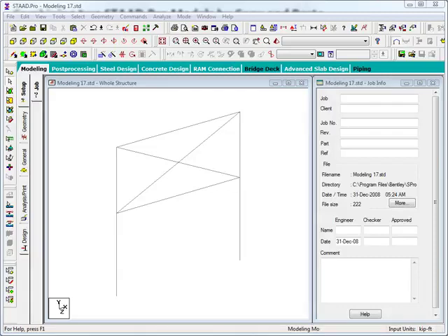And then we can envision that these multiple engineers advance their portions of the project simultaneously, and then at whatever predetermined time that the individual models are complete and ready to be combined, they could be brought together in the way that we just did with the braced frame and the portal frame, all compiled into one single model at which point the final modeling steps could be completed, and then the entire combined structure could be analyzed and designed.